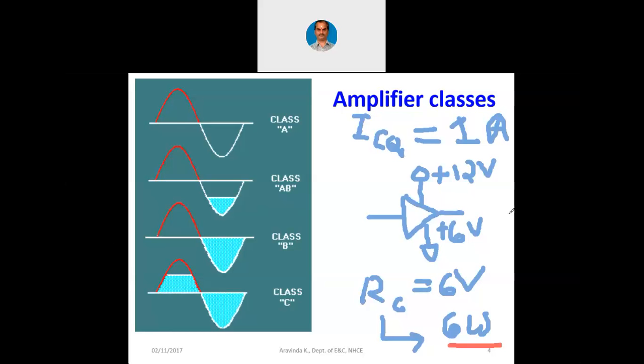We have a power amplifier which has to be class A only, means it has to work with both the cycles of the signal. When we speak, we will always end up with this type of signal. Why? When we speak, the vocal cords vibrate up and down, and the vocal cords are going to produce a pressure on the diaphragm of the microphone, which is to and fro.